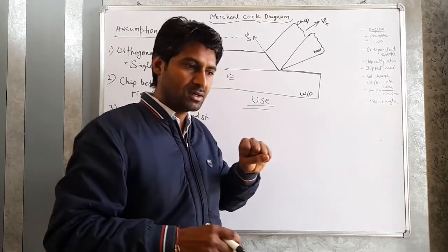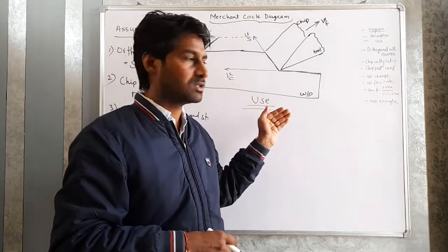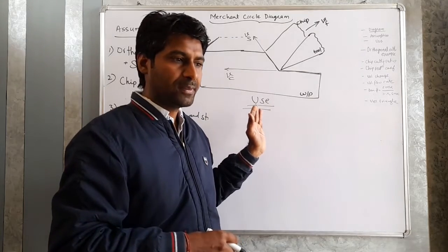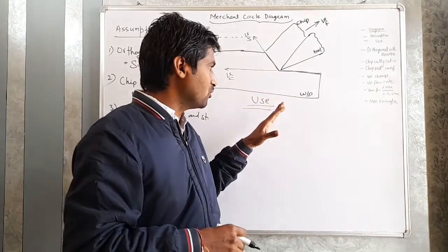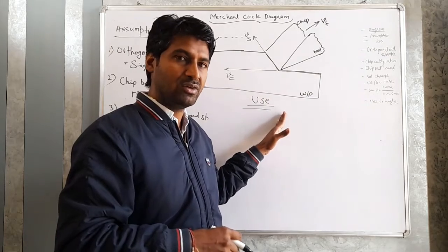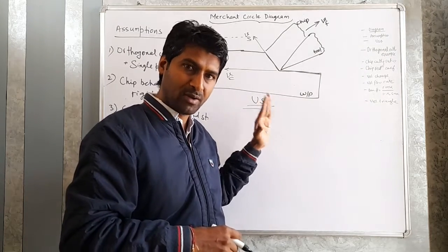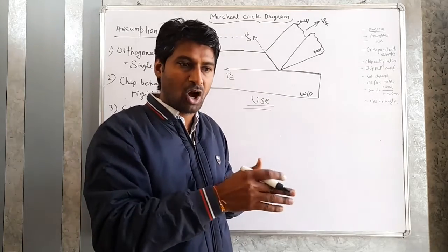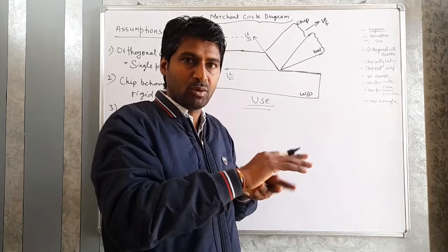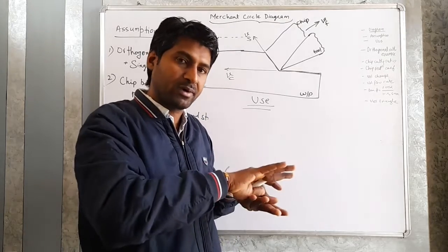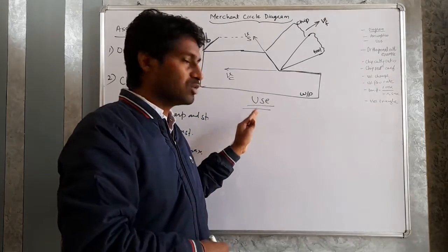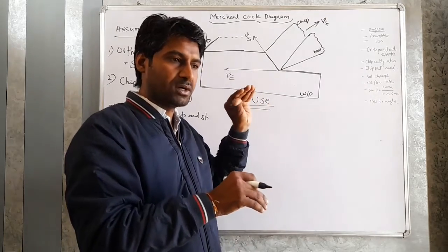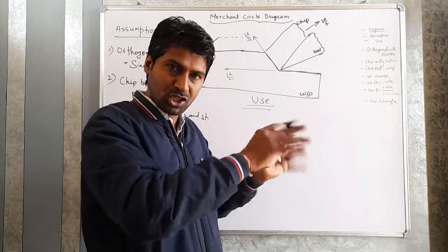How much power is consumed during the cutting operation, we can find with the help of these cutting forces. Once we find the power, we can estimate what type of motor, and with how much power, we can use. It will also help to design a machine tool, fixture and tool system.